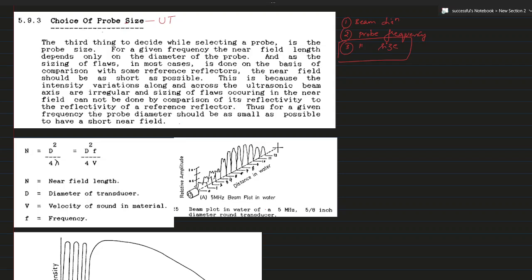Today we are going to understand how the probe size is selected in ultrasonic testing. Before going to understand this, we understand the concept of near field. This is an ultrasonic probe, if you assume, and while releasing the ultrasonic beam, it is of this nature.